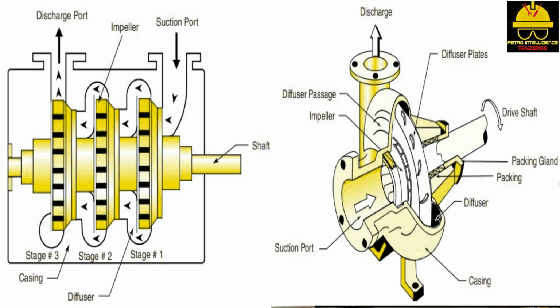As high-velocity gas moves through the diffuser and into the volute, kinetic energy is converted into pressure as gas speed slows in the ever-widening volute before exiting the discharge port. Because compressor performance is linked to the compressibility of the gas it is moving, centrifugal compressors are more sensitive to density and fluid characteristics than are reciprocating compressors.